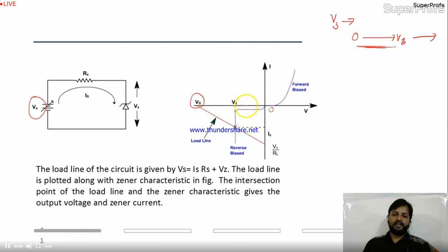The current is 0 in the circuit, or I can say a very small current, that is the leakage current, because the diode is in the reverse bias. So in the reverse bias there is no current, or if you have current in the practical diode, it will be very minimum, that is the leakage current or current due to the temperature. Okay. So here, I equal to 0 in this region. This is the condition below breakdown.